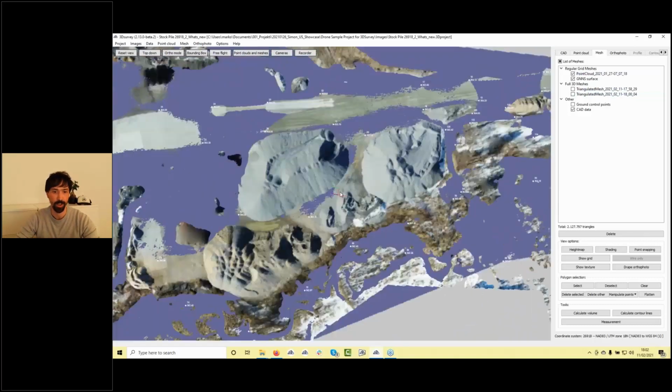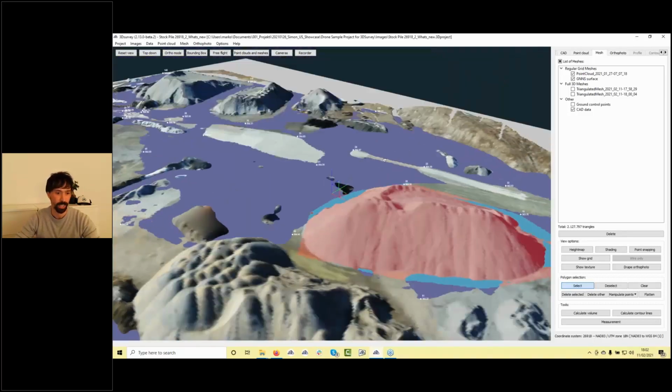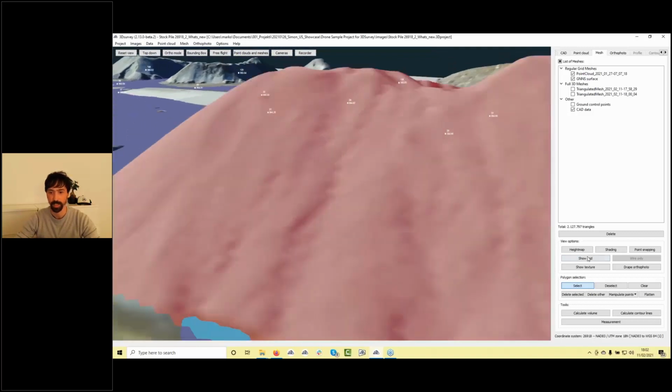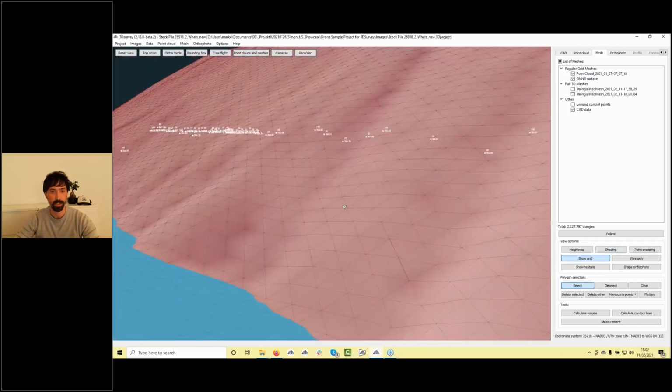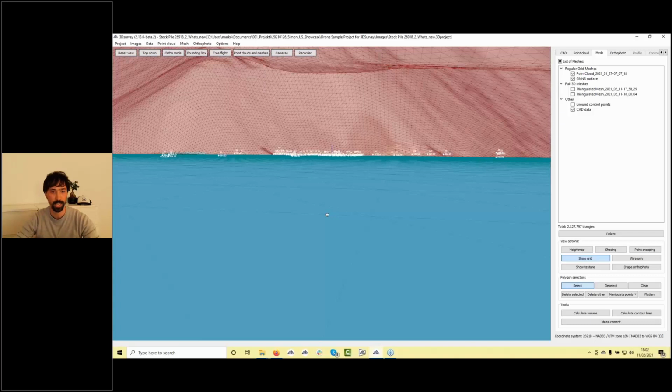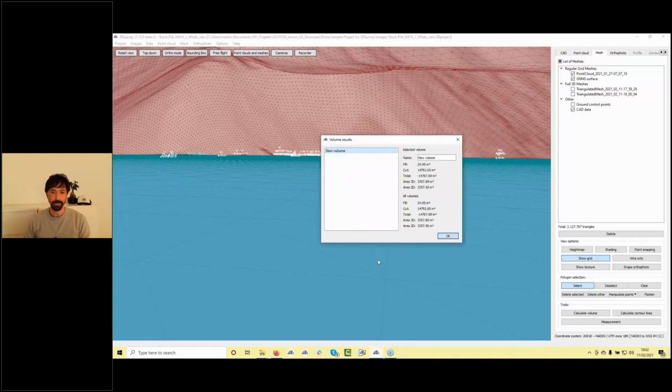Okay, much better now. And just quickly select our area of interest, upper surface, lower surface. I'm in between those two surfaces. Okay, not sure if you can see it as nicely as I can, and calculate volume from those two surfaces. So now everything will work, and here we have a cut material. Why cut? Because my first surface is realistic, the second one was designed.